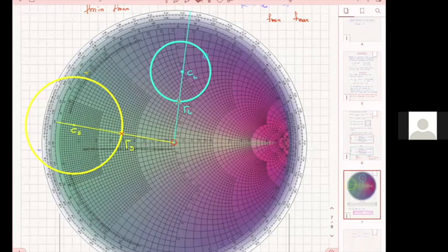Yeah. And is that also true when the amplifier or the transistor is conditionally stable? Yes, if it's conditionally stable, it depends on where your transistor is going to be. Usually, all of the transistors we will see will have S11 and S22 less than 1. And in that case, you are inside the Smith chart. All right. The times when you have a sliver out here, you remember we saw in stability, this is becoming more difficult because obviously you're already far from the Smith chart, whatever you do.